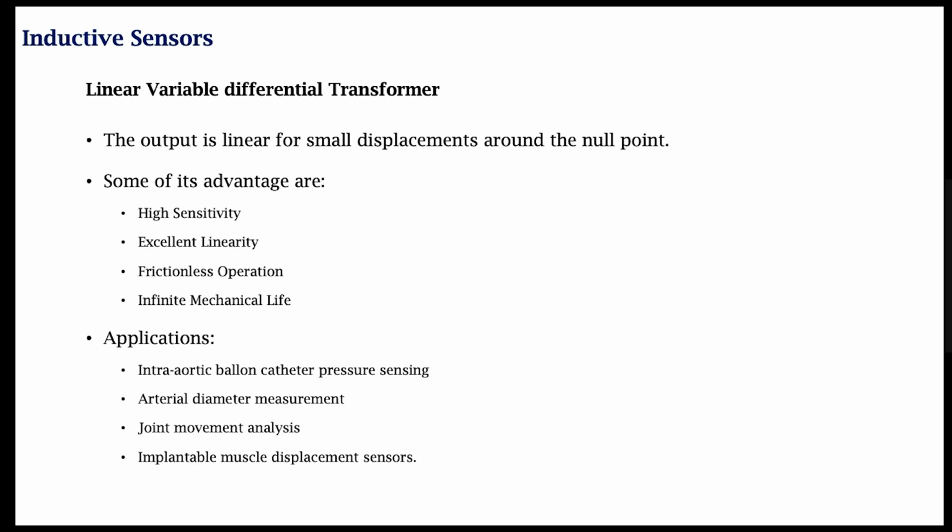And if you use hermetic sealing, what do we mean by hermetic sealing? Hermetic sealing is a situation in which, because we are only interested in magnetic coupling, the core itself is inside an airtight compartment. So that means I can also insert it inside a fluid, like for example blood, and then the movement will happen inside, and there will be no blood entering inside, or nothing from inside the armature or the core will go to the blood, but still the movement itself can be detected.